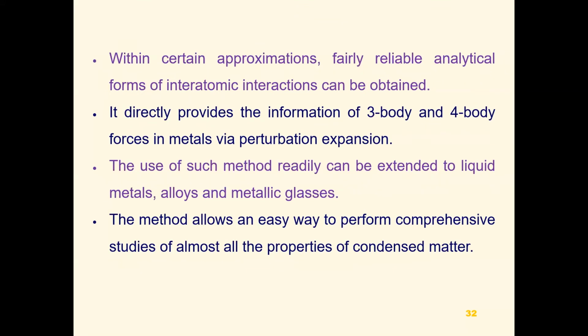Within a certain approximation, fairly reliable analytical forms of interatomic interaction can be obtained by using this method. It directly provides the information of the 3-body and 4-body forces in the metals via perturbation expansion. The use of such a method can readily be extended to the liquid metals, alloys, and metallic glasses.